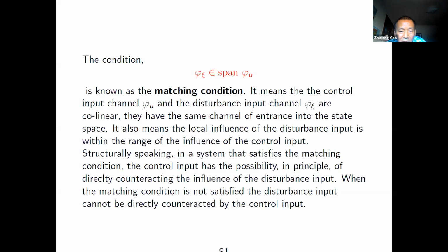you apply the typical second order ADRC configuration, then that disturbance on the electrical side is matched. But if we ignore that and treat it as a disturbance on the mechanical side, then our disturbance compensation will always be lagging behind, because the disturbance in electricity is at least 90 degrees ahead of the mechanical disturbance.